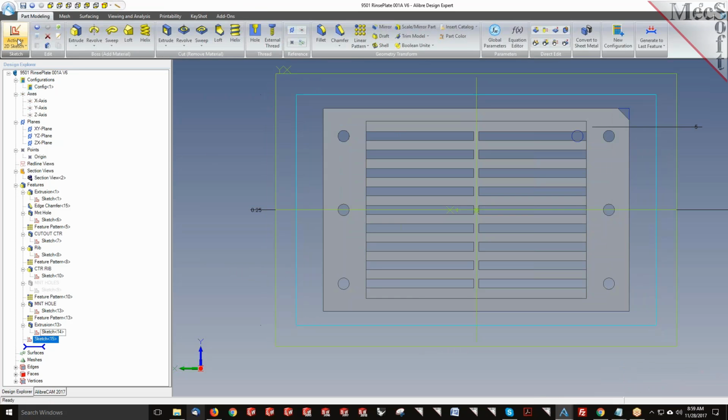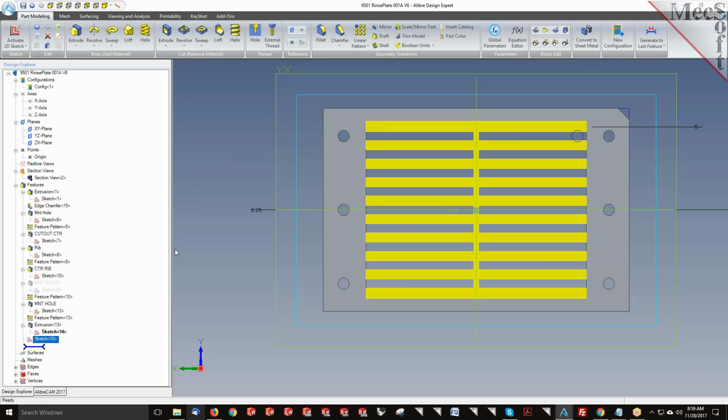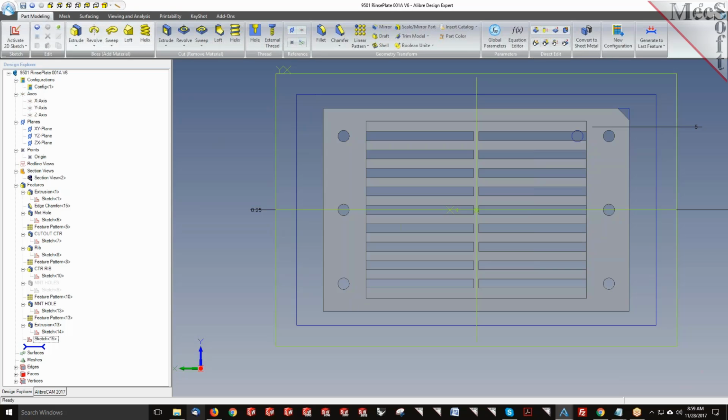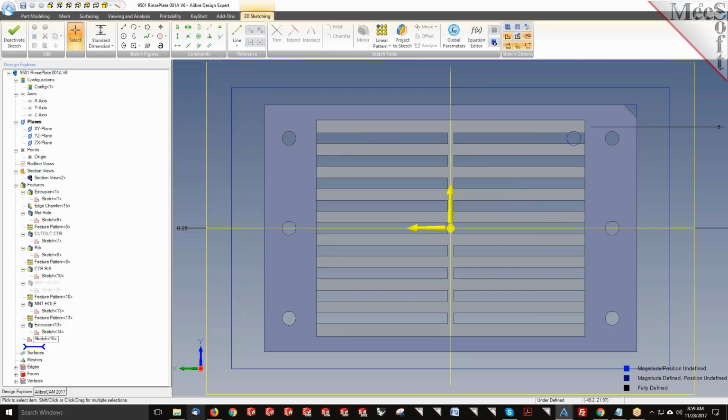Now we have the sketch drawn, and I can go ahead and activate a new sketch in here. Maybe you can just insert points, or you can even put in circles. You don't really have to make it a 3D model. You can specify a circle, and you can use dimensioning for it. You can say what is the dimension, 2 millimeters or 2.5 millimeters. You can also add relationships in here, how far it needs to be, right? From this to, you can add dimensioning between these two, and then you can also specify constraints in here. Once you have those created, I'm just going to go ahead and add a few circles in here.